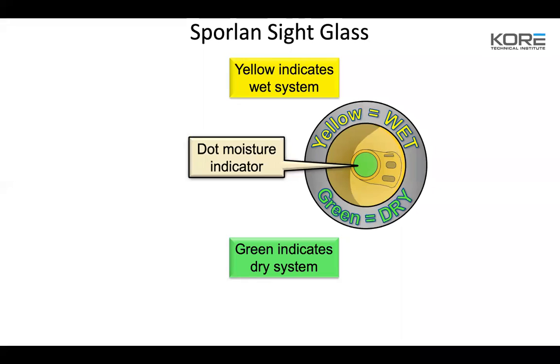Sight glasses are a very good tool in a lot of systems for us to know what the liquid is doing, make sure that we've got a solid column of it, and make sure that it's not coming and going. The nice thing about seeing that, and you guys that have worked on Costco racks have seen this, is that you'll see that liquid leave and come back and leave and come back, depending on when those large systems go into defrost or when the coil's going into split and unsplit. So it's good to understand what that's doing so that when you do run into an actual low charge situation, you're making the right call.